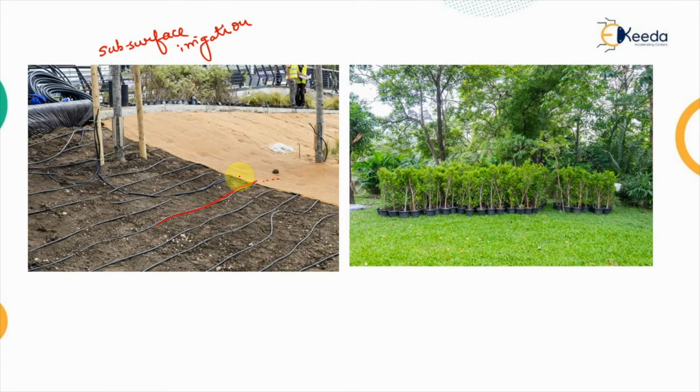And when the water is flowing through these pipelines below the ground level, that means the evaporation loss will be reduced to zero only, and that is also preventing the overuse of the water for the irrigation purpose, which is very pertinent in case of the surface irrigation methods.